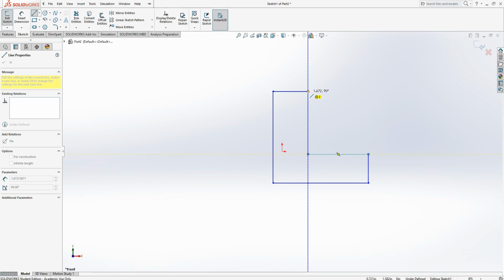So I'm going to close this shape. And you'll see my icon. There's a little bullseye. That means dot on dot. So this will close a loop. And that line to the right of it, vertical line, this is a straight line. So I'm going to click and close. Now, if I did it correctly, I should not be drawing any more lines. I have one continuous chain of lines.